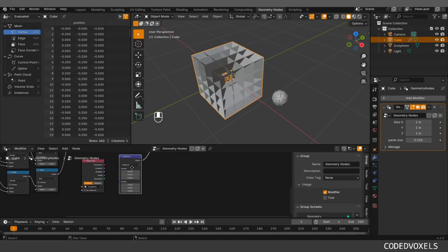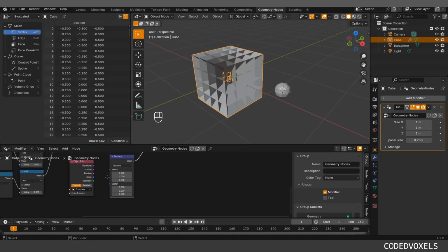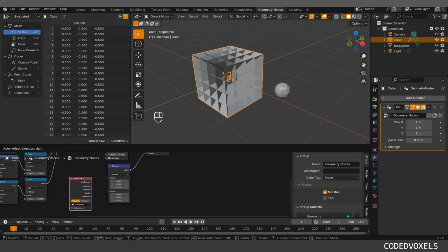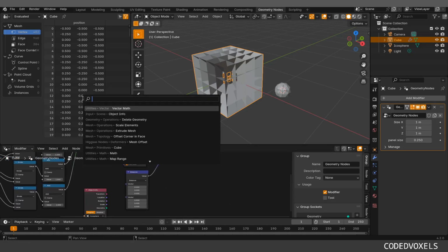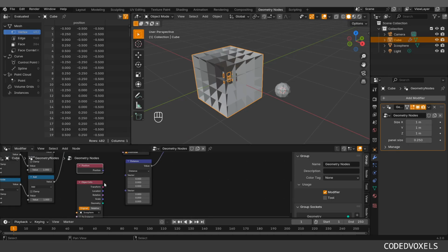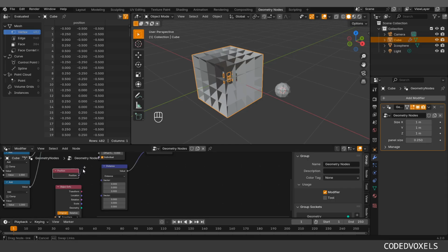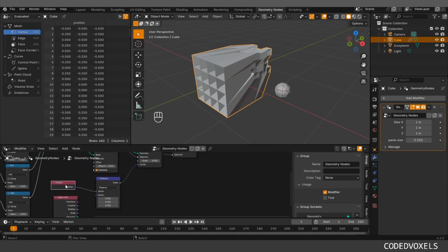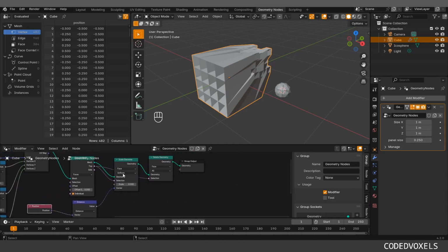And what we're going to need is not the distance from 0 to 0, but the distance of the face to the icosphere. So Shift A, Position. This is probably one of the difficult concepts to grasp, but right now this is kind of a self position of what, and then you can know of what by going down into the nodes, and it's of the face, right?